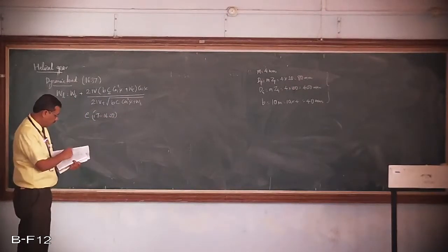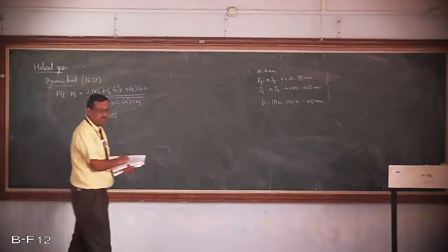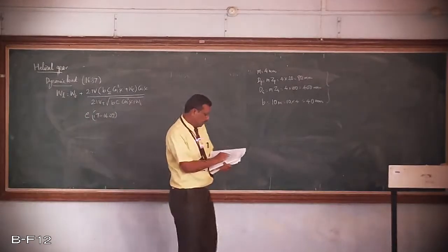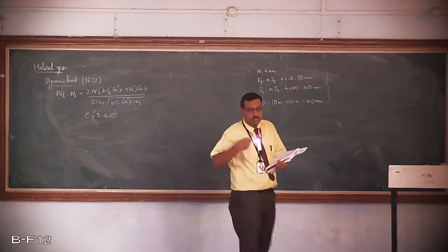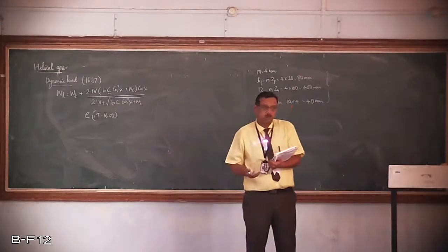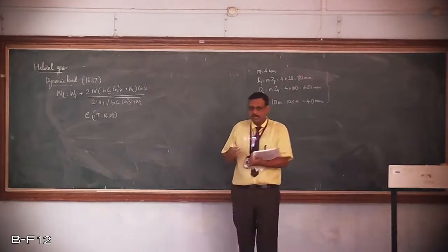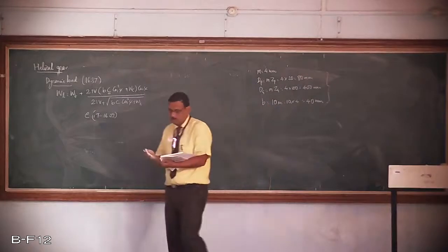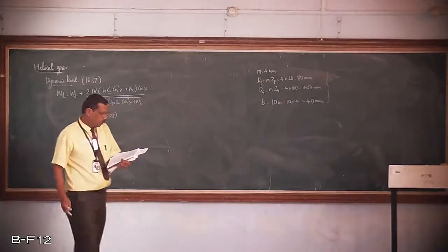We have module of 4 millimeters. Let us take class 1 gears because the speed is less. Class 2 is accurate and class 3 precision. Therefore, higher the precision, the error will come down because machining will be accurate. The lesser the errors, the lesser the dynamic loads. That is so simple. Therefore, class 1 industrial commercial gears.